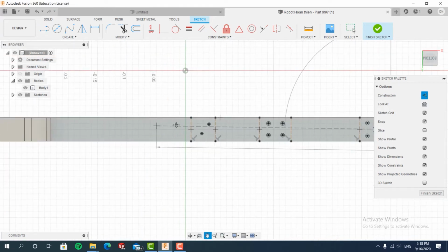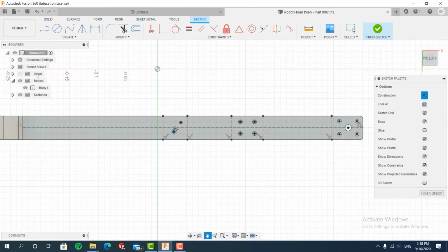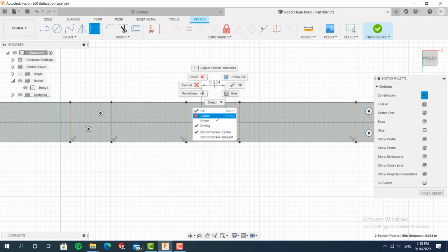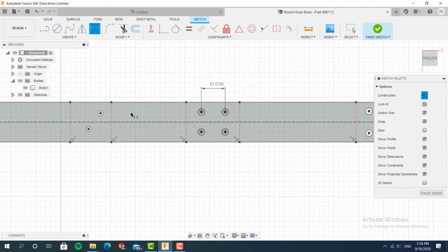Pocketing is just the act of cutting out parts of different extrusion and different parts of the robot to reduce the total weight. It can also give you a lot more space so that you can put in different parts, maybe get an axle through somewhere, things like that. This can be easily done with things like hand drills. You can just cut out some circles, and that will be the first thing I teach you here, just how to draw out circles. This might seem simple because, well, yes, it is very simple, but there are a few things that you need to consider.